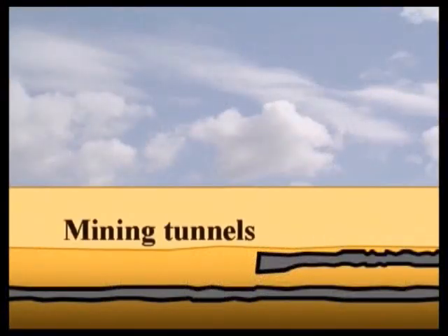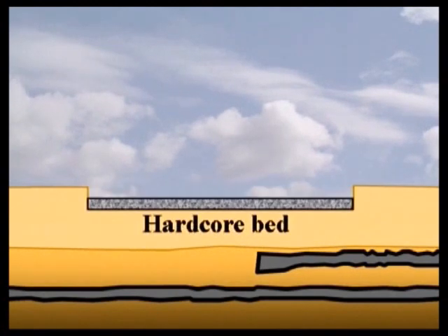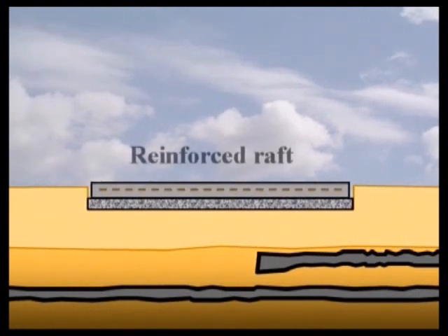Reinforced concrete rafts can also be used where there's a risk of subsidence. They're quite common, for example, in areas of present or past coal mining. They can also be used on very soft clays or compressible fills where the depth of a firmer stratum precludes the economic use of strip foundations or piling.